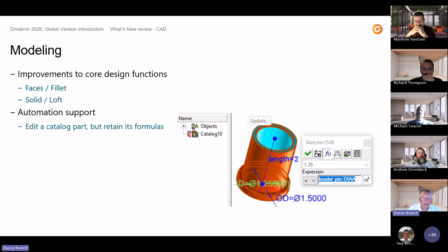This one is related to formulas and catalog parts, because it's very common to see that some of the parts being driven in the assemblies are catalog based, very common. But when the catalogs get changed, whether it's our update, the user, whichever, the parts want to do an update. And that type of update is not mandatory. Users can ignore it, but we've all seen they don't like to, right? They see those red marks in the tree and they want to resolve that, so they do an update. They just can't help themselves, and then all the formulas get dropped.